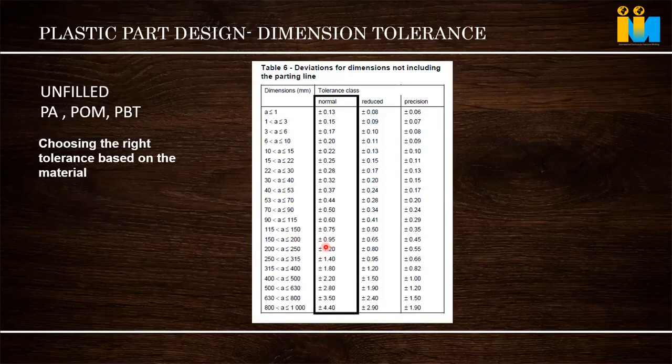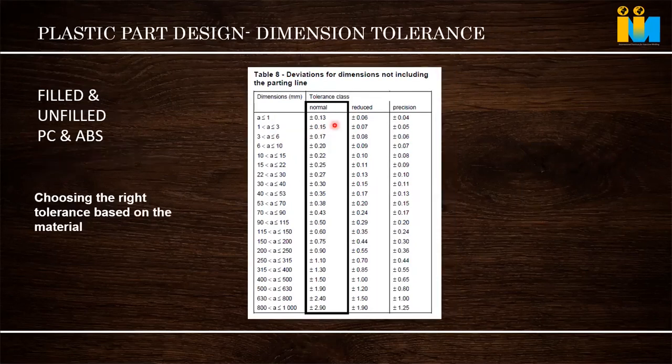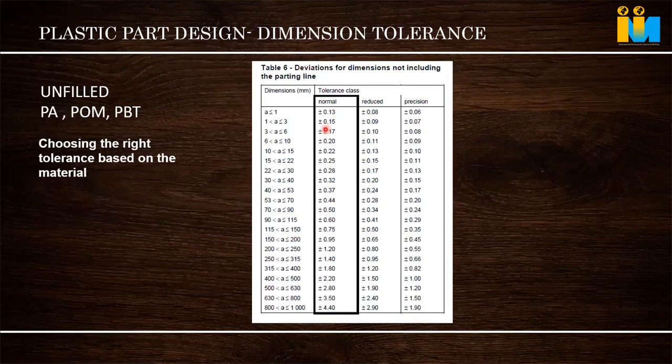I take an example. Now this is a crystalline material. Now you see, same last condition, 1 to 3 mm. Okay. The lower side is almost the same, but for precision tolerance it cannot meet 0.05. And as the length keeps on increasing, this has a warpage property, very difficult to control the warpage and shrinkage.